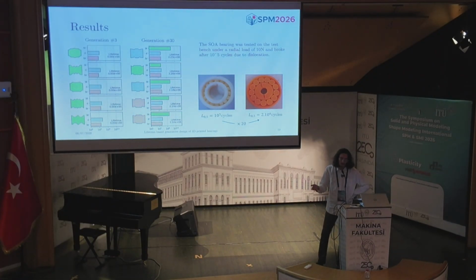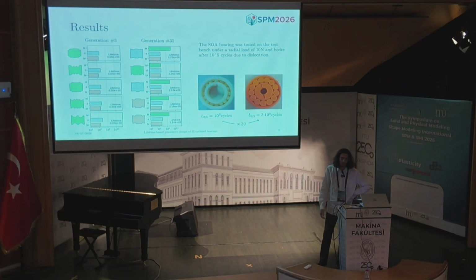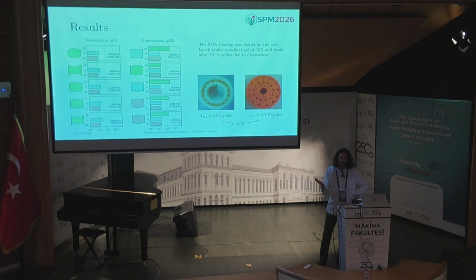But on my side, I also did the test with Anycubic, so with a Creality 3D printer, and each time the conditions we have to set are the clearance and also the angle of printing, because there are some printers where, when there are fewer layers, we can have a better angle of printing. So these two parameters have to be set when we change the printer, but this is really easy to set in the framework. Thank you.